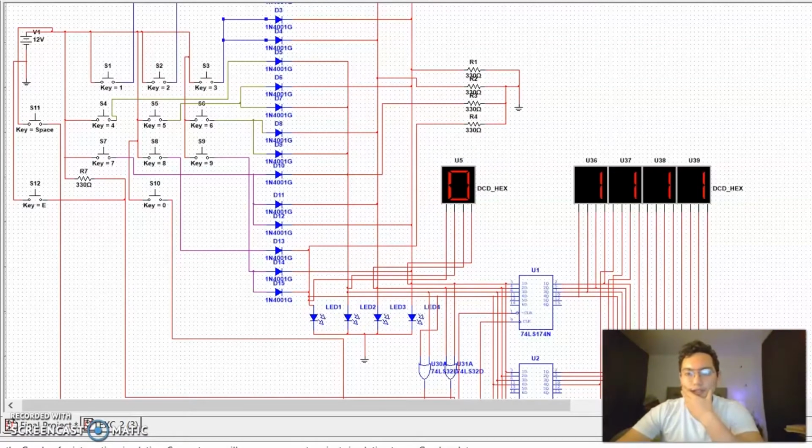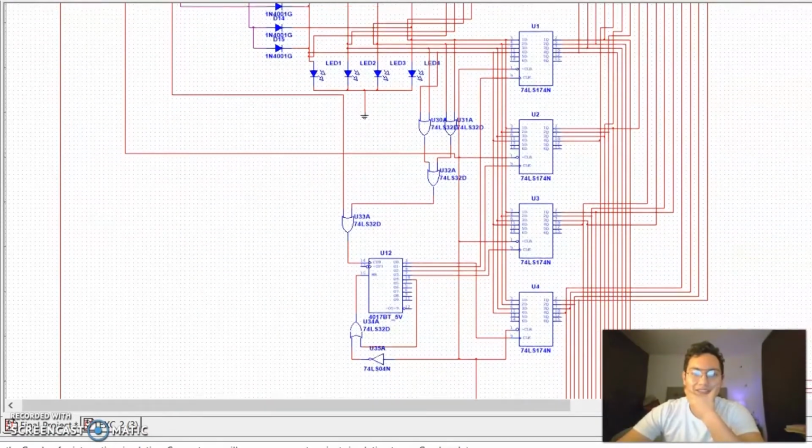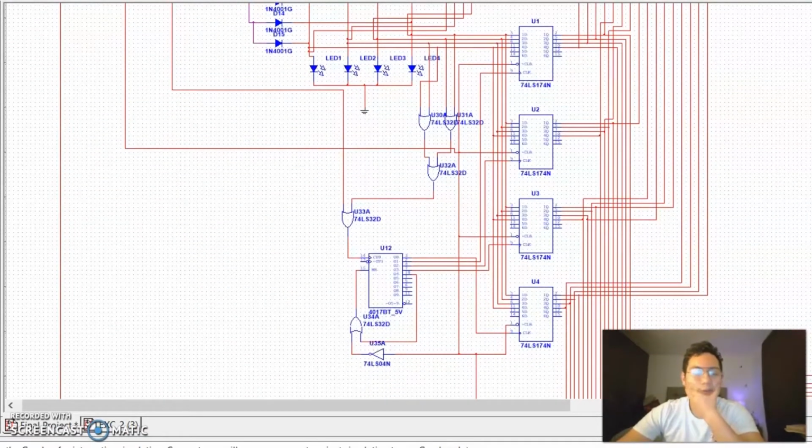The second part is here. This was quite a problem because all of these are E-type flip-flops, because this is like the first step of the memory bank. This is the first memory bank in this vault, because we need to have 2 memory banks. The memory bank for a preset password and the memory bank for the password you are entering.